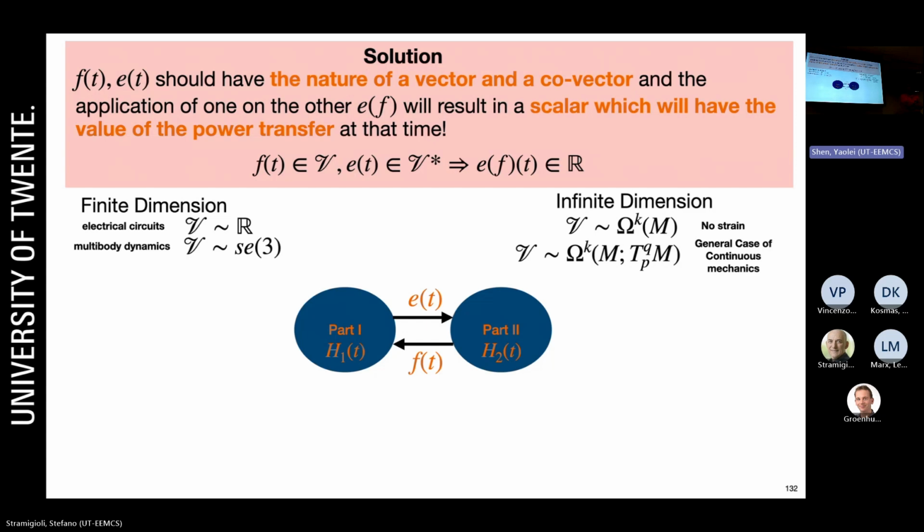People in other fields have not recognized it, and you will see that we'll introduce objects called junctions in bond graphs, which actually represent Kirchhoff's laws. And then you will see that you will need a vector structure because you want to be able to sum efforts and flows. Now I decompose only in 2, but sometimes I want to compose in 3, and I want to say how these 3 elements are connected to each other. So it will all become clear.